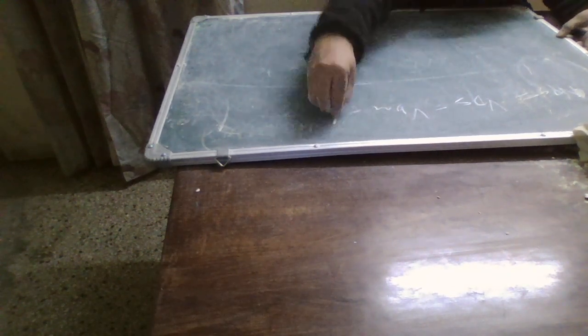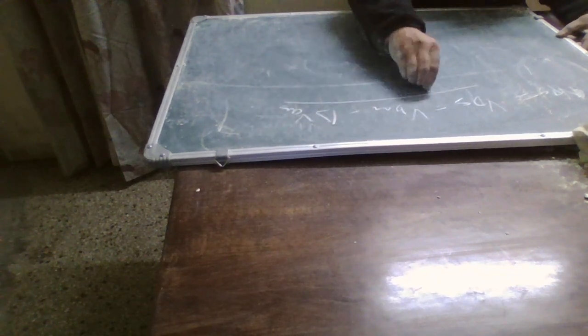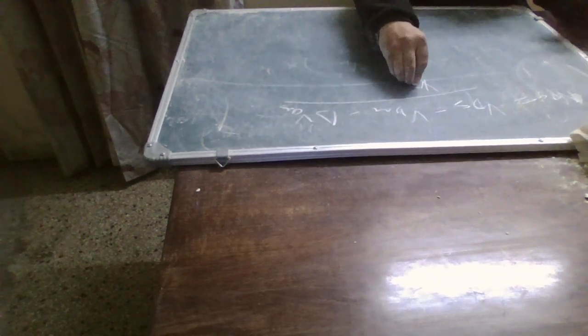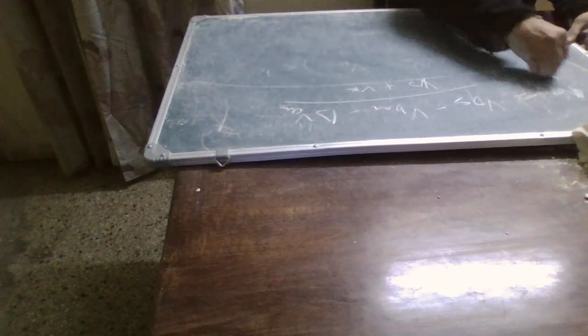V out is the output voltage and VF is the forward voltage drop of the secondary rectifier, and we are getting the ratio NPS maximum. This would be the drain to source voltage I just mentioned minus V bulk maximum minus delta V clamp, divided by output voltage plus forward voltage drop. This is the maximum value.